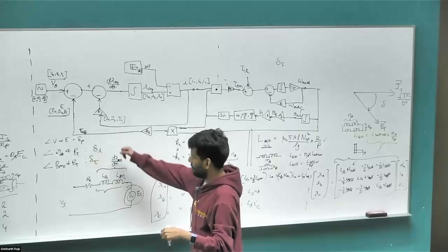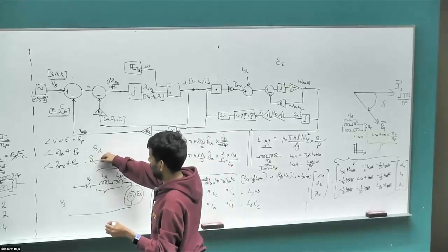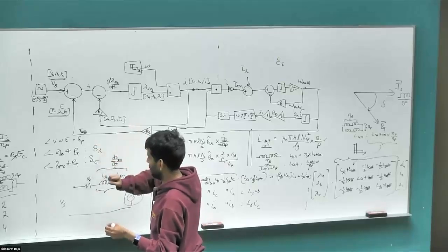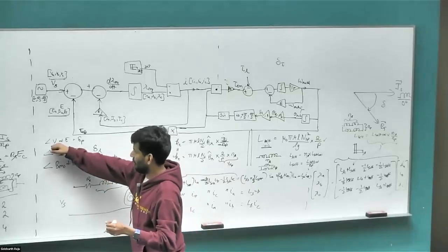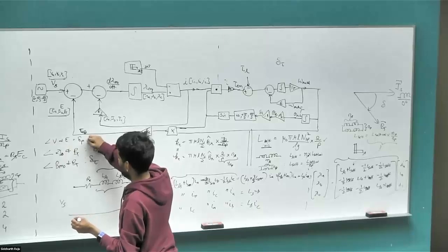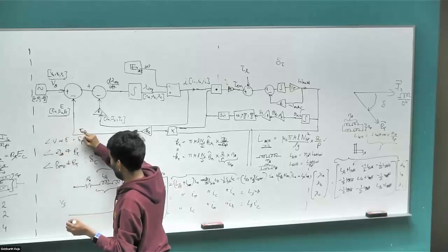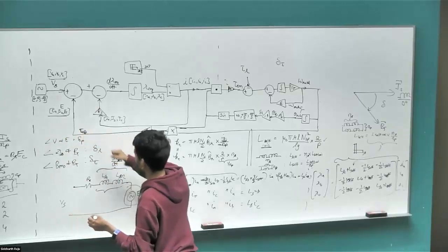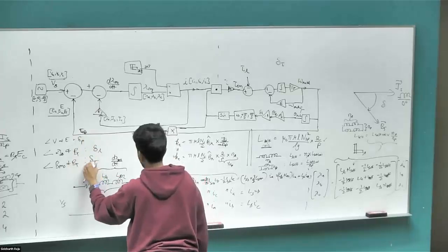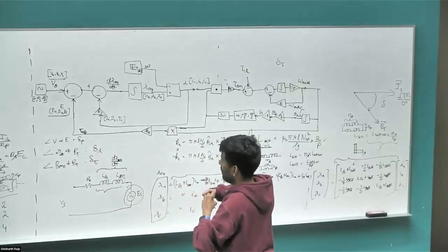All these three angles will be computed, and when you run it, you'll see that if you say you want a fixed current in the model in the init file, then when delta tau becomes 90 degrees, later it will become unstable, left hand side will be stable. If you say you are applying a fixed terminal voltage, delta P becoming 90 degrees is the point where the motor would have the maximum amount of power, above which, after 90 degrees, the system would become unstable. When this reaches 90 degrees, delta tau would be well past 90. In the model that we have, it goes to about 125, 130 degrees. Okay, so with that, we are done with the permanent magnet synchronous motor model.